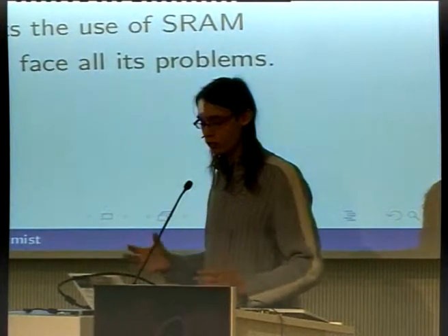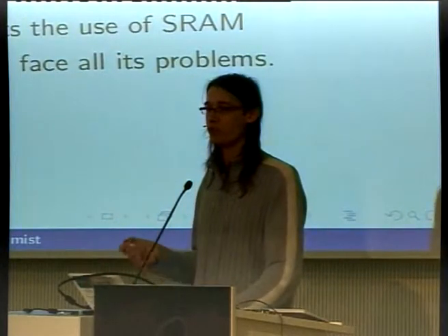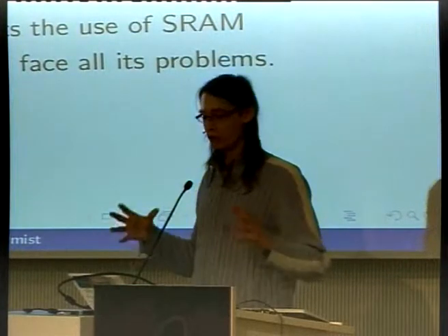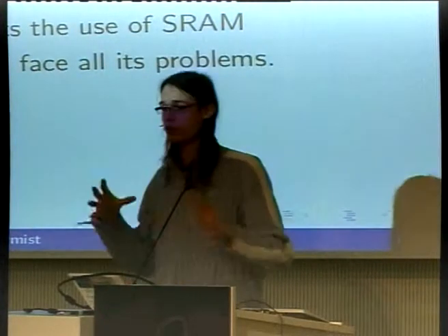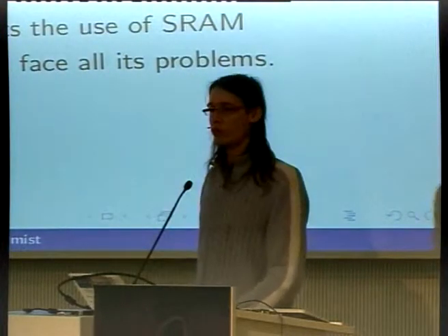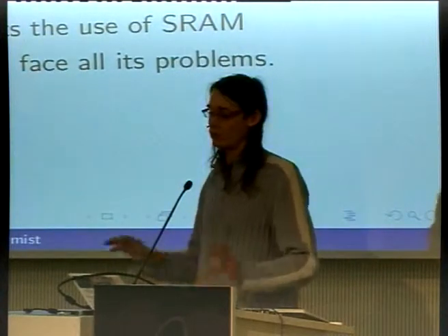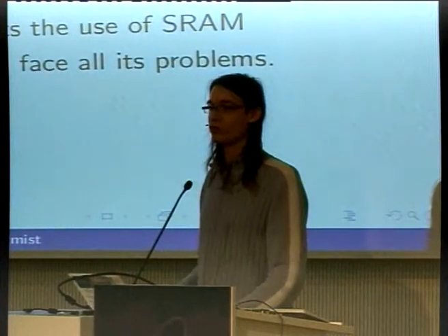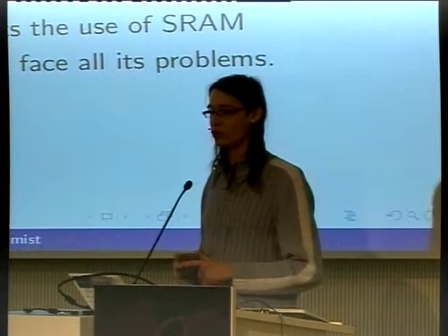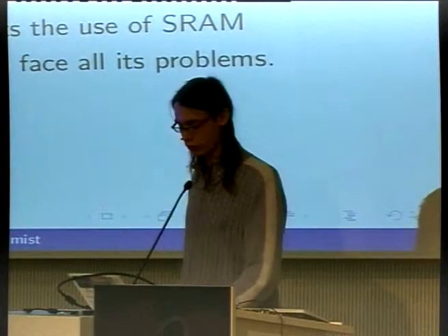And the required memory size prohibits the use of SRAM, because a very easy memory technology to use is SRAM, which stands for static RAM. But if you need a big memory size, SRAM gets extremely expensive. For example, if you buy a 4 megabyte chip of SRAM, it will cost like 100 euro or something, so that's out of the question. So I have to use DRAM, like in computers, for example. You know, SDRAM, DDR SDRAM, DDR2 SDRAM. This is the type of memory that I have to use because of the cost constraint.